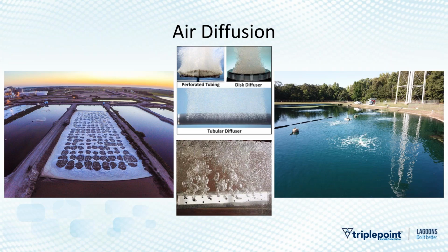The benefit of coarse bubble, though, on the other side, is that they do mix very well. They rise turbulently, so there is a little bit of a boon to their aeration from that perspective. Fine bubble aeration is going to be about half of the energy cost of surface aeration, the power cost, and then coarse bubble aeration is going to come in about 20% higher, 30% higher than those fine bubble numbers. So coarse bubble tends to come right in between.